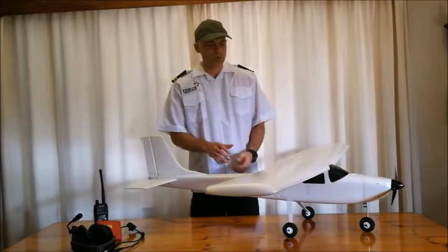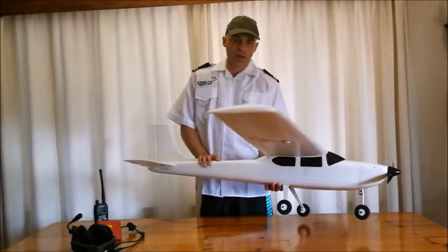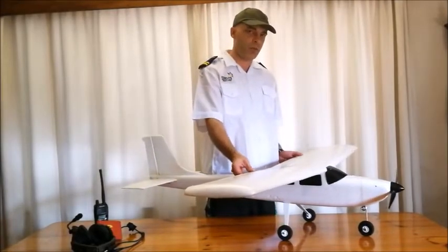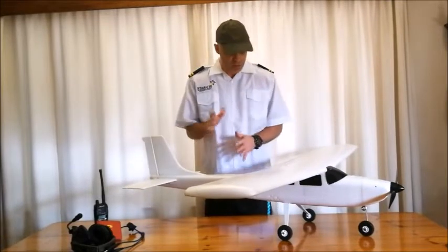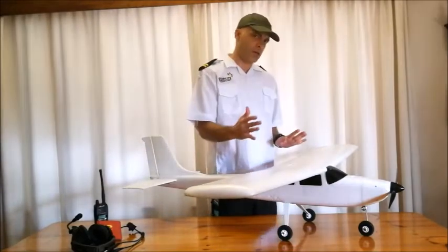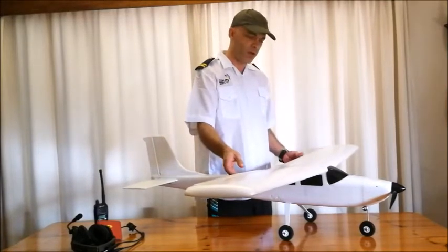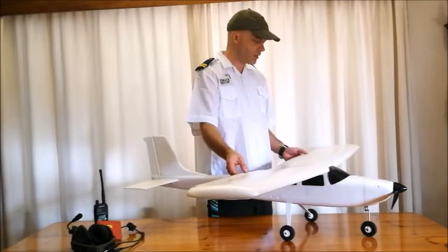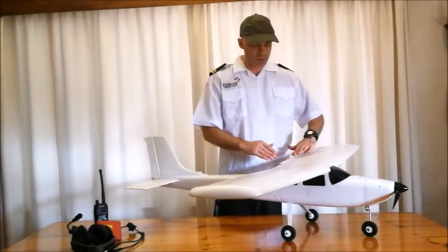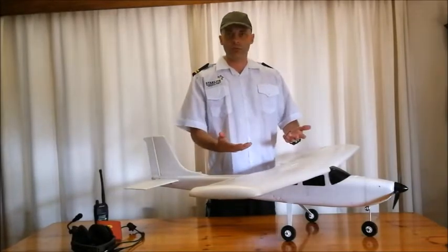And then we've got what's known as roll. Roll is a motion of the wings tilting towards the left and towards the right. The roll motion is performed by the ailerons, which are on the main wing, and they're able to move upwards and downwards. Okay, so now that we've got the three basic motions in place, let's see how it works. When a roll has to happen, one aileron will move upwards, the other aileron will move downwards.